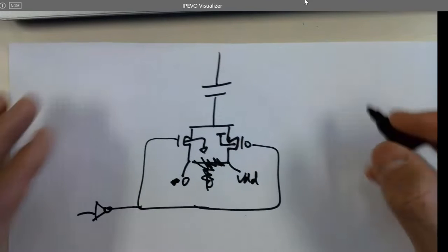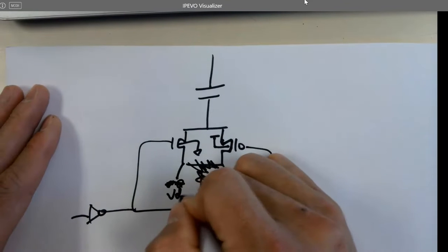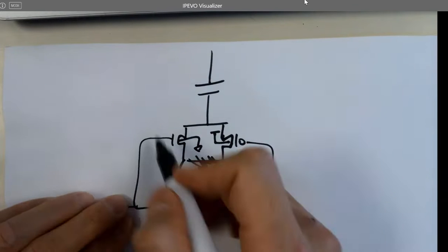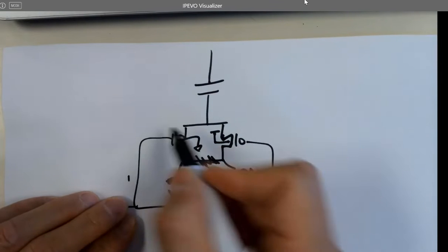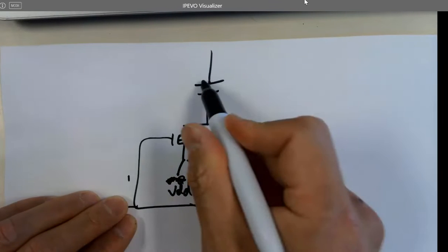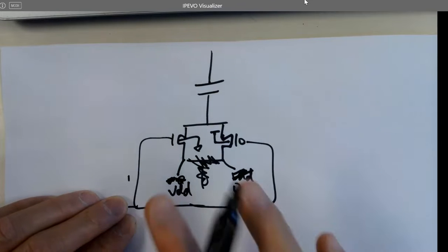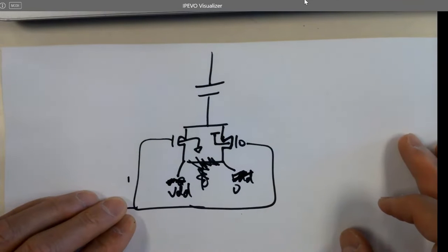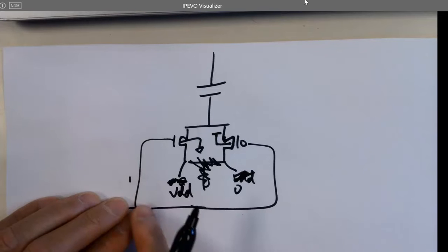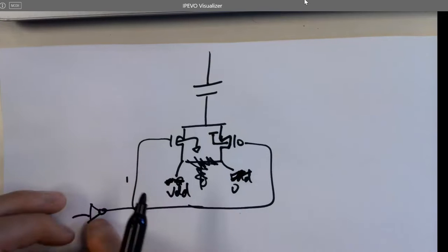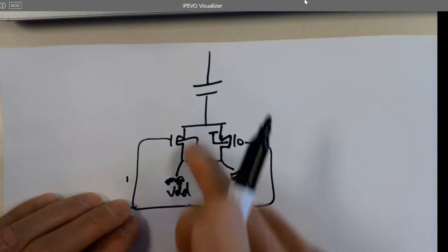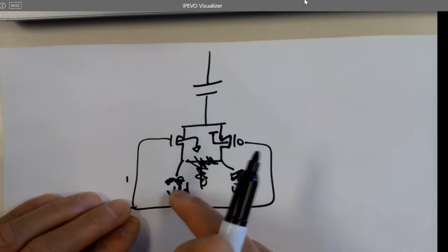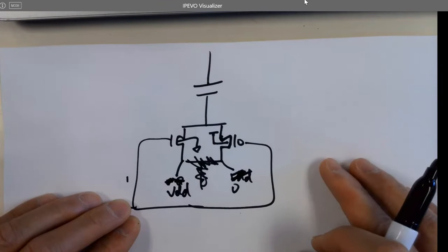Because for example, previously you got a VDD here. That's why he has to put a VDD here, because when you got a one, you want to turn this on, so you want to pass a one here. If you flip it, you got a one to turn it on, but it's passing zero, so it's wrong. It's okay if you have a one but you don't invert it, but you have to have a VDD for the NMOS, letting the NMOS pass VDD, which is not ideal. We don't like it, remember?